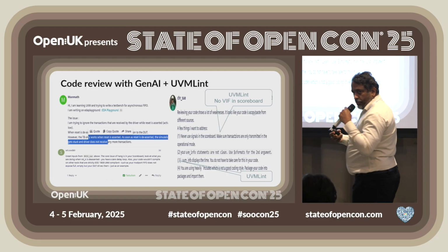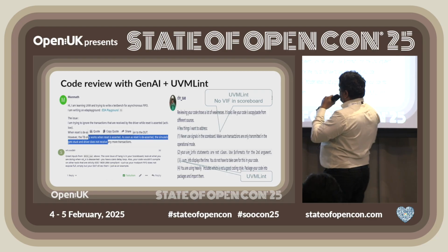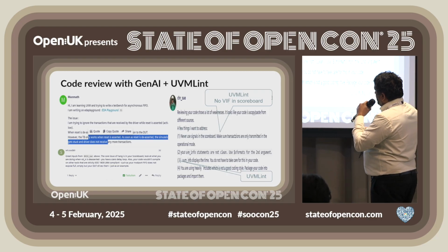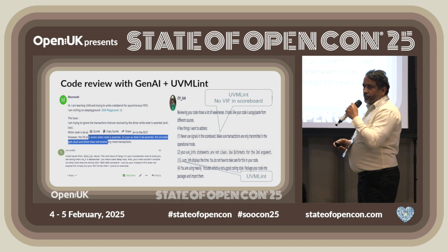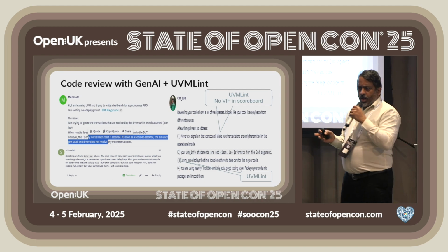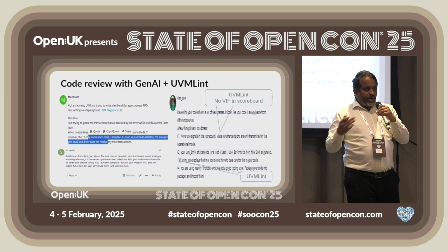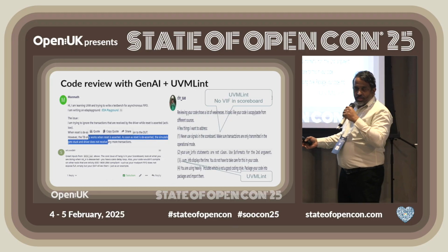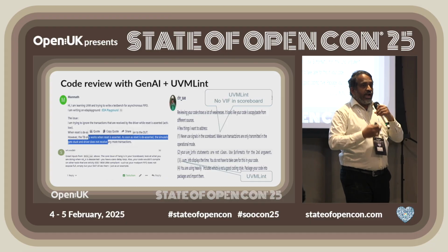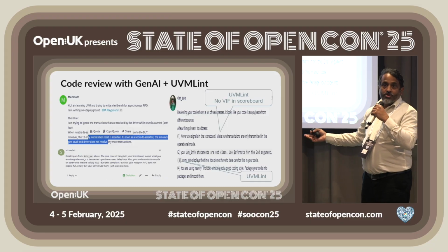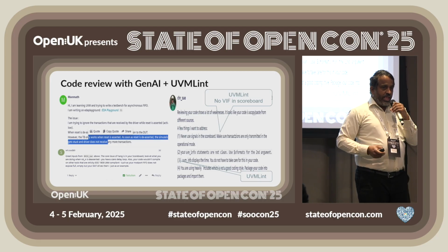Again, I'll be available outside if you want to talk in detail, but this data is available on the web in the Verification Academy. Essentially he said, when the reset is asserted, the testbench works, but as soon as reset is de-asserted, the simulation gets stuck. And it's definitely nothing to do with you as an individual. Most of us, even after 20 or 25 years, face this problem, right? There is a zero delay loop somewhere in your scoreboard, just that you don't see it, and you want an additional pair of eyes. That used to be your seniors. Now it could be your GenAI, right?